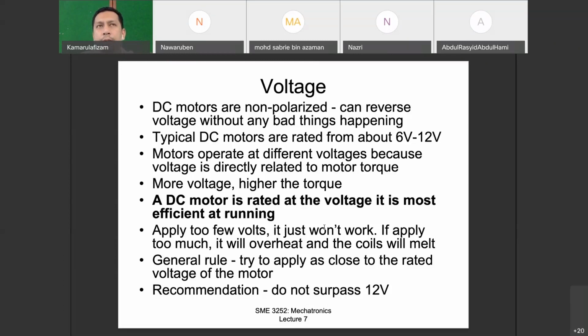Okay, if you give less or more than that, everything will shift, but you will still observe that the motor still spins. Again, I mention a 12 volt motor, if you give 5 volt or even 1 volt it spins, but slow. And you can hold it with your hand and it can stop. If you give 12 volt, you can find the rated torque and RPM. If you give 20 volt it will also spin, but its rated values will all shift. You give 30 volt, maybe it burns, that's all. So that is about motors.